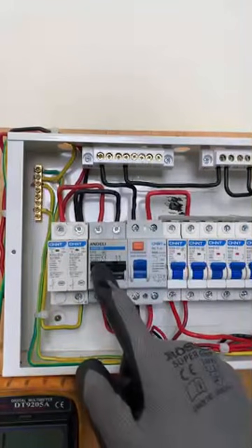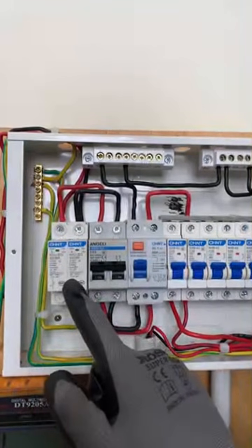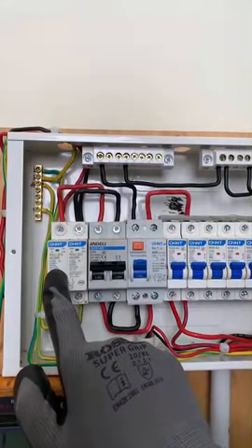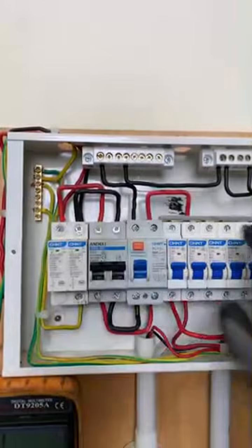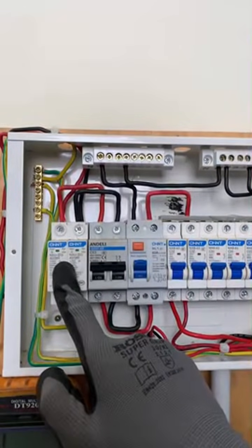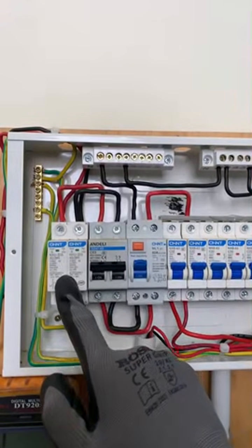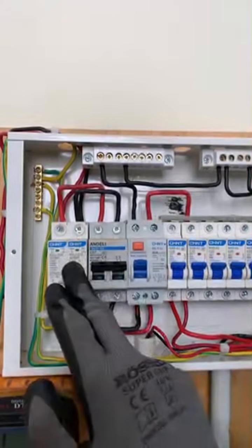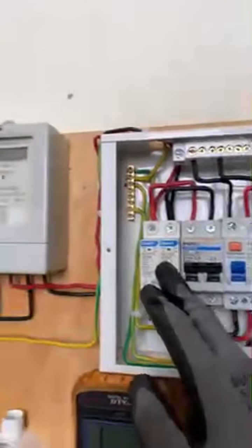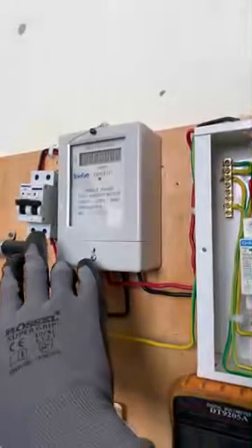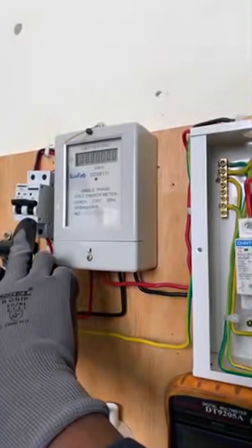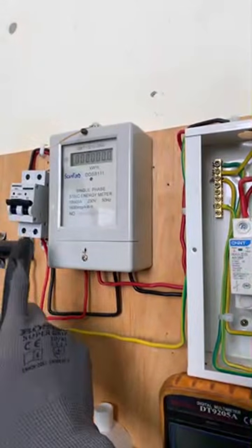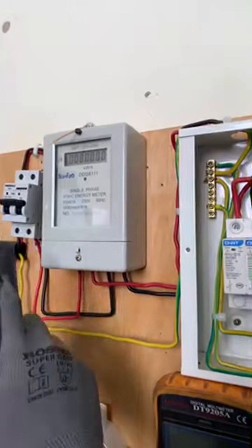What is the purpose of an SPD, surge protective device? As the name goes, it protects the circuit against the surge which comes from outside. If it is internal, it is only limited up to the meter. So assuming that we have a surge here, how can a surge come about? Loose connections on the neutral. Suspect number one, a loose connection on the neutral.